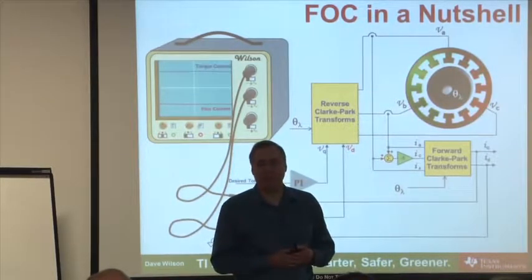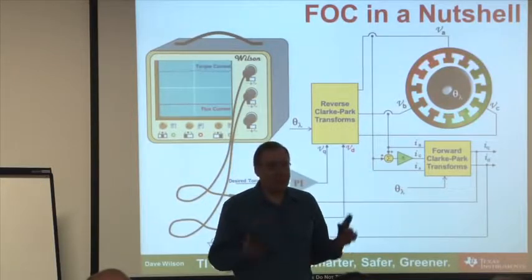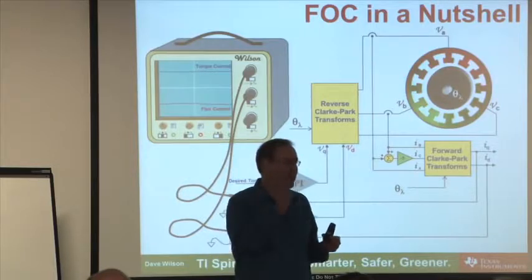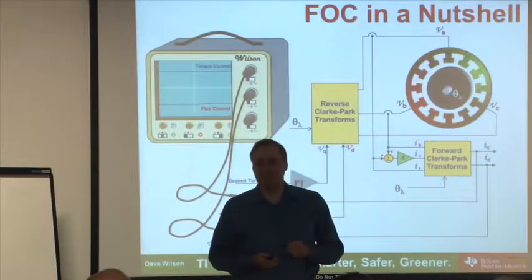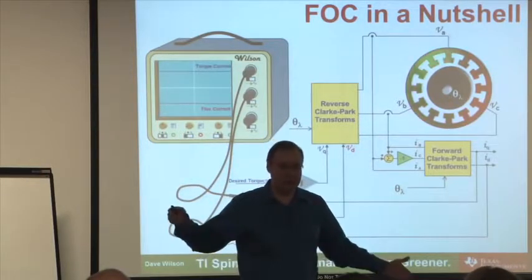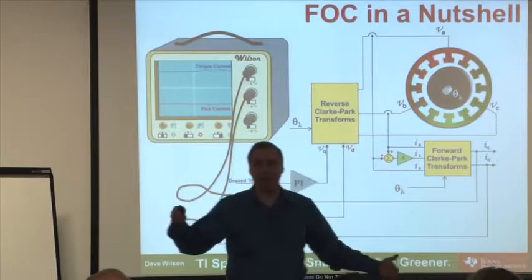I mean, that's how fast we can whip through it. So the field-oriented control part of it is not really hard, especially if you know the rotor angle. If you don't know the rotor angle and you have to calculate it sensorlessly, then your equations can start blowing up, and we'll get into that later this afternoon.